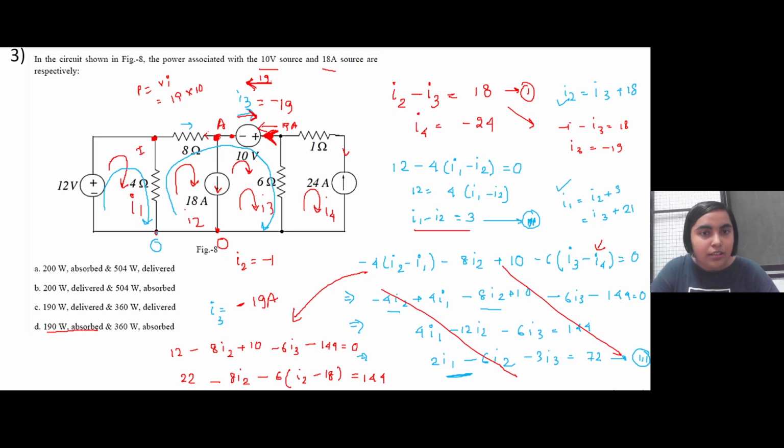So you cannot say that since 19 ampere is coming through this particular branch, 18 ampere is going here; you will find that 1 ampere current is flowing through this branch. These two branches are connected as shown here, so this entire loop is not independent, right? This is a node which is the intersection of this particular 8 ohm resistance and a current source.